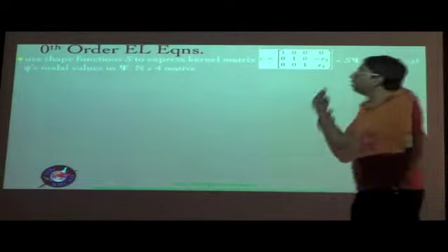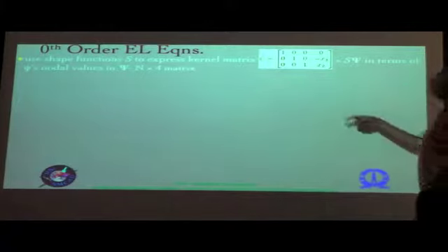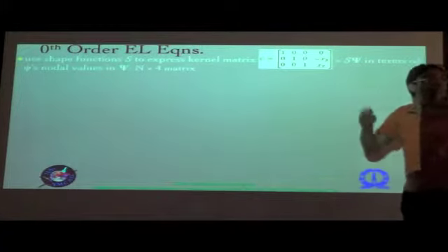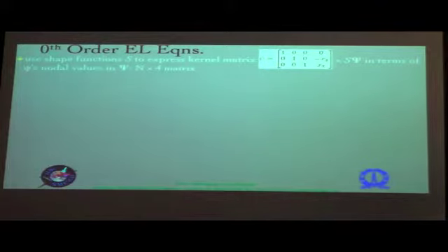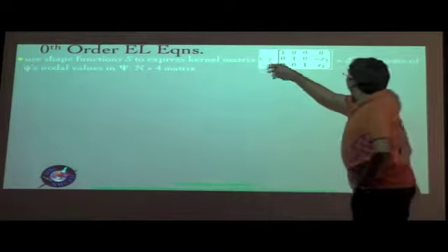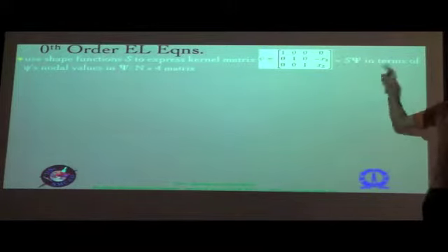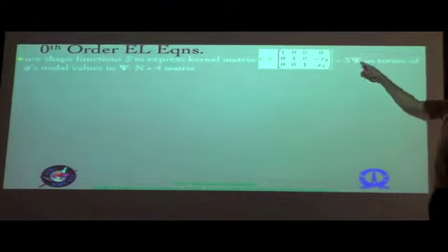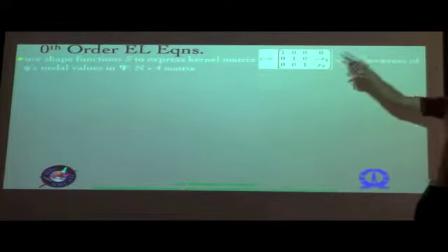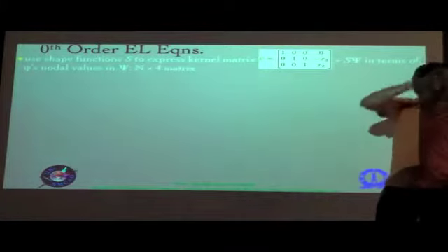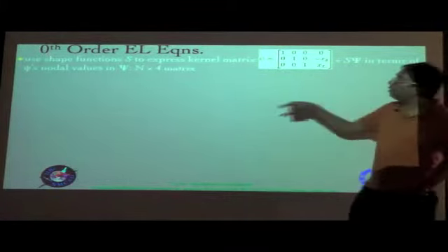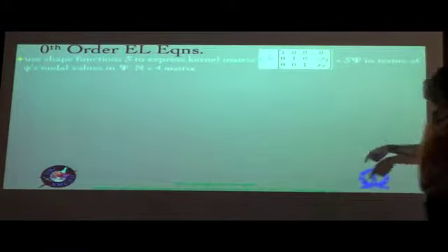So now use the shape functions S to express the kernel matrix Xi, which is basically this, which is again something which should not contribute to the warping because those are things that have already been accounted for by the rigid body degrees of freedom, which are contained within your gamma 11 bar and the kappa bars, right? So now that Xi, we will write it as S times Xi. Once again, remember that your S is a 3 by n matrix, and your Xi, capital Xi, would be an n by 4 matrix, which would contain the nodal values x2 and x3 of all of the n nodes that you have, and that's why you have an n by 4 matrix over there.